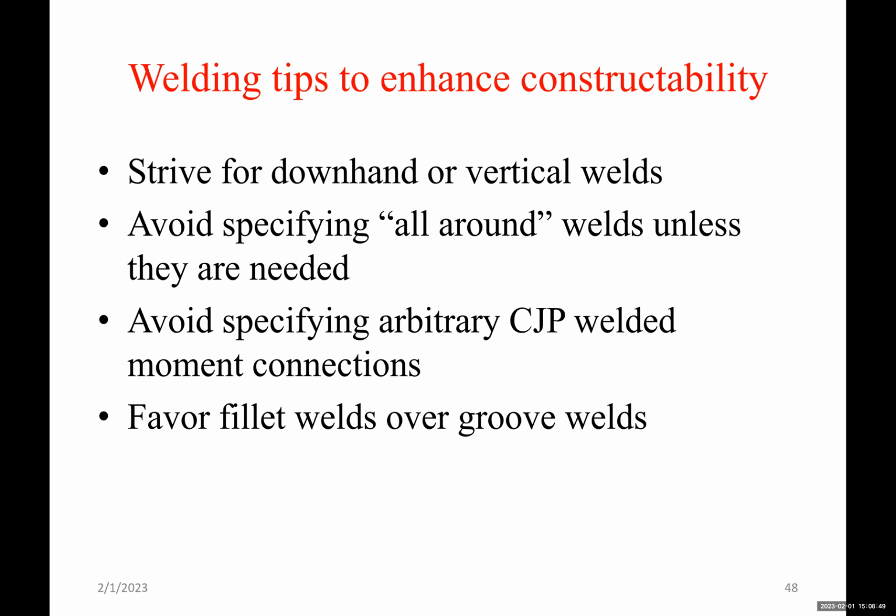So the width of the flange is, say, 3 inches. So that's in your way. So you cut it 3 inches plus, let's say, ½ inch, to allow fitting that properly. So the answer is yes. The more detail you can get into, the more it means that you understand your structure, how it's going to be built and how it's going to be erected, okay?